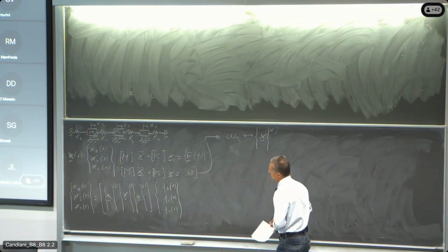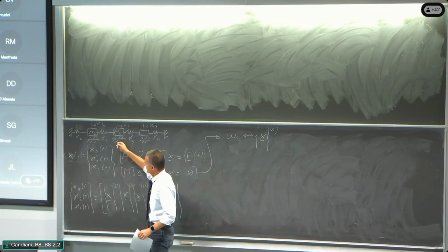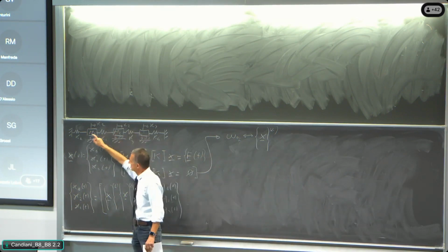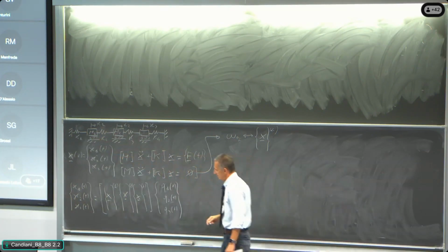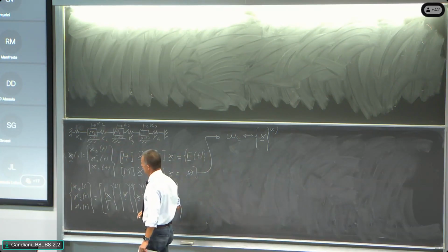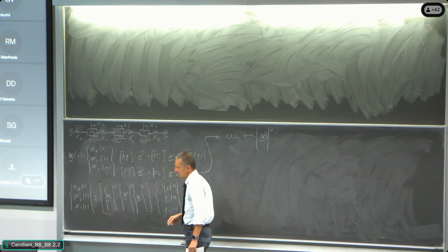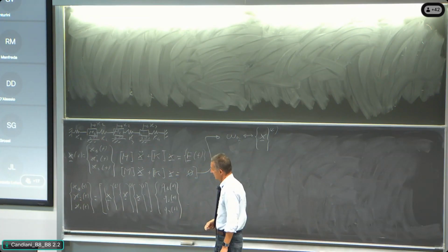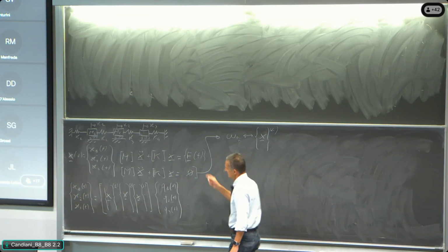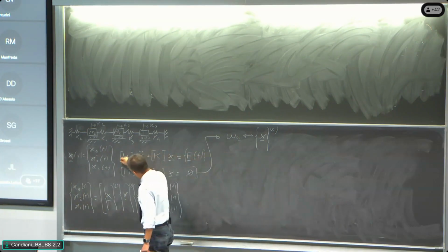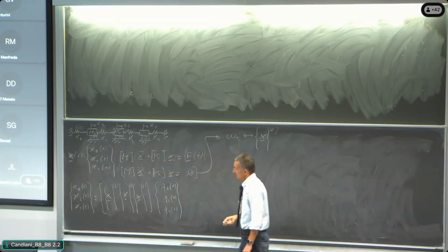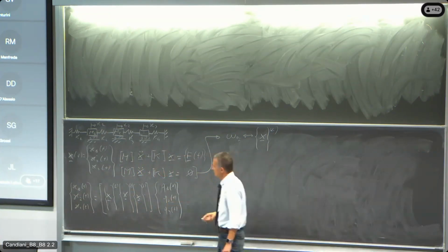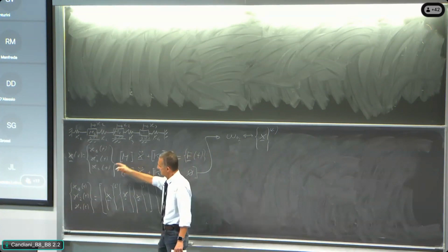All right, so we assume that we have a system, n degree of freedom. We are taking care of the elastic problem, assuming that it is fully linear, small displacement. At the moment, we don't take note of any damping, so we are speaking about the elastic problem. For analyzing the kinematics and studying the dynamics, using typically the Lagrangian approach, we write the n equations of motion of the n degree of freedom system.